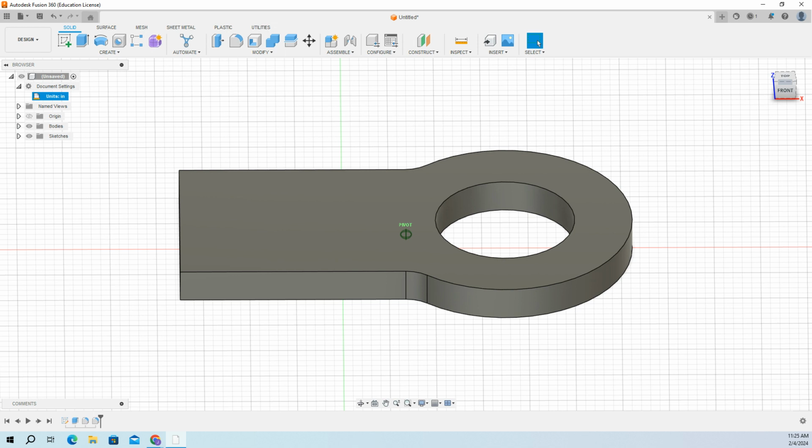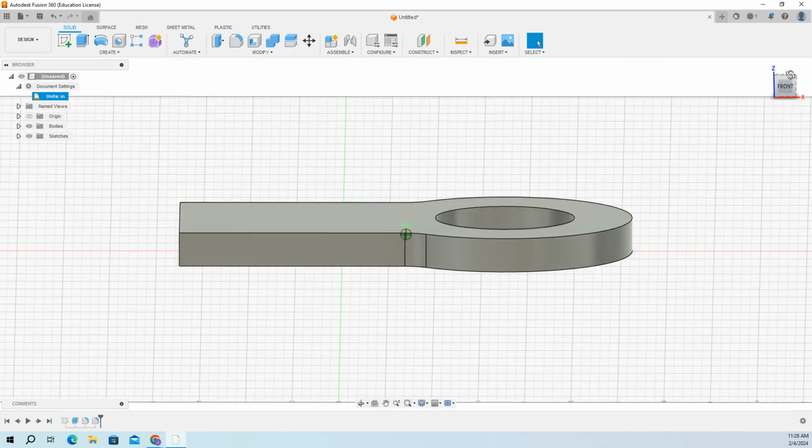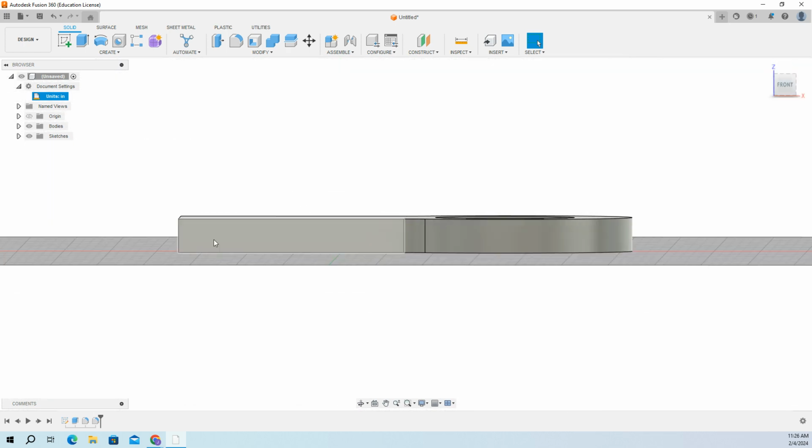And then what's easiest for me, and then maybe what's easiest for you. All right, so now from the bottom all the way up, let me look at this version. They tell us from the bottom of this, that's 0.37. Then we go up 1.37. So we have to add a 1, right? And then we also have to add 0.75. So we're going to extrude it up 1.75.